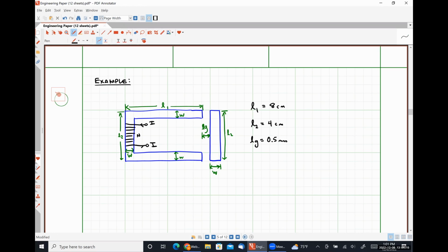So we should see that the length of our air gap, or the distance that our air gap occupies, will hopefully be smaller than the dimensions of our magnetic circuit usually. If we don't have that, we're going to lose a lot of flux. Okay, so if we want to minimize core losses, which we'll talk about on Tuesday, we want our air gaps to be very small.